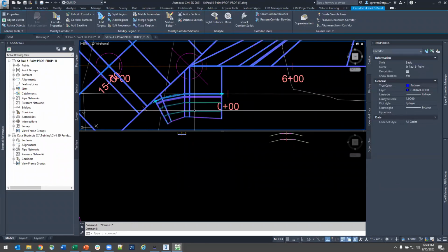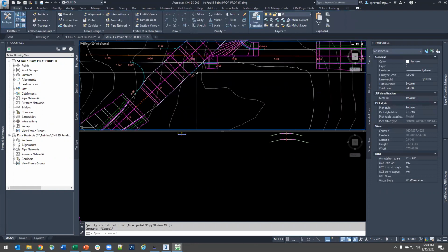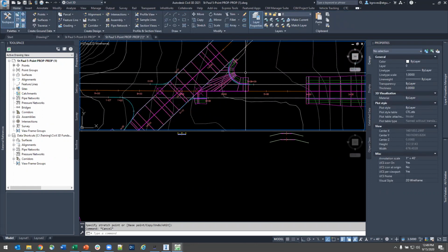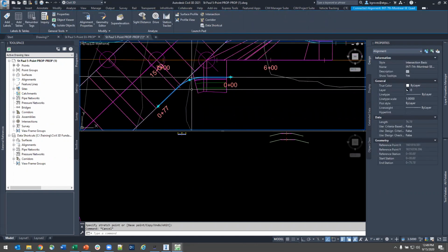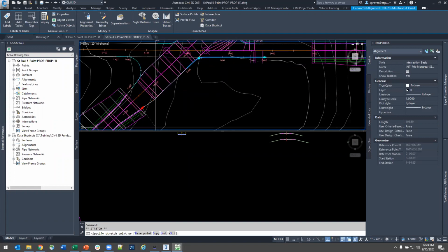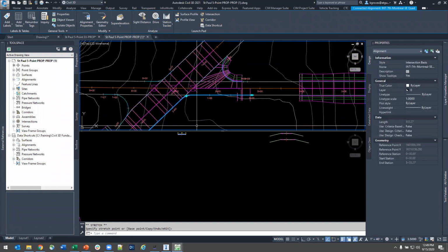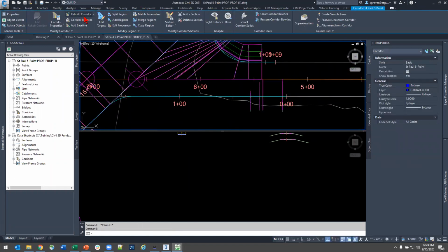Now, I'm only going to have time to do kind of the southeast quadrant of this full intersection here, but we can see that I'm going to run into issues in these low angle corners, right? So my initial connected alignment for this due south intersection isn't very long. And there's no way for me to make my northeast connected alignment smaller so these half roads can connect cleanly to my full road. So this is going to require me to bring my connected alignment overlap pretty far out across the connection between my other two alignments. But that's okay because everything's dynamic.